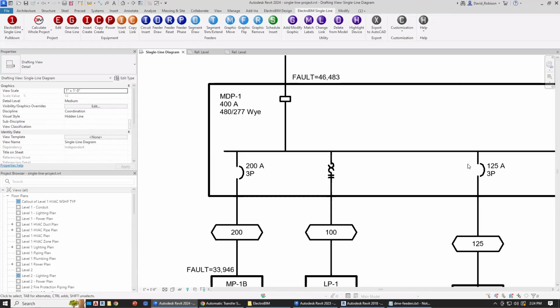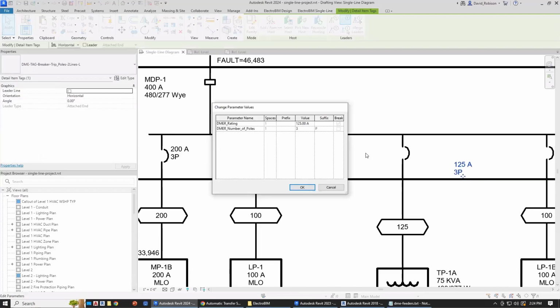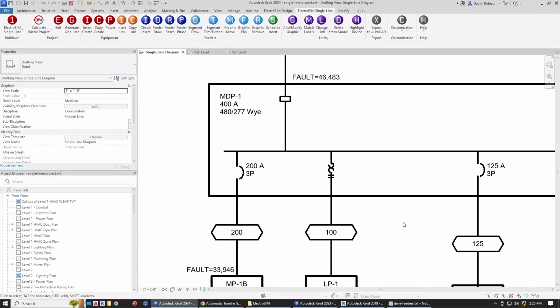You'll notice that we did lose the label here. That's because the label is associated with a Revit project. It knows to then put this label in because this label is not embedded in that family. It's a separate annotation tag, so you can move it around. Revit doesn't let you embed those in your families. So we have a system where you can create a project that has the family and then that label so that it knows to use that label when it uses that family.